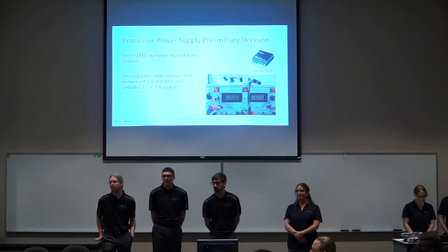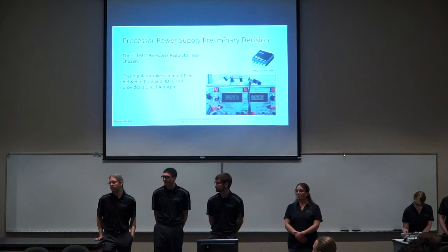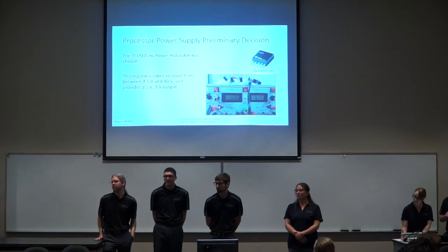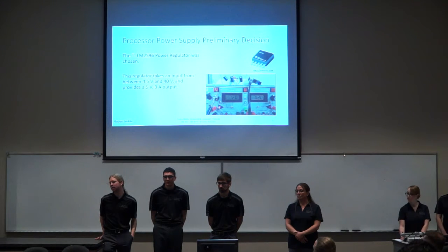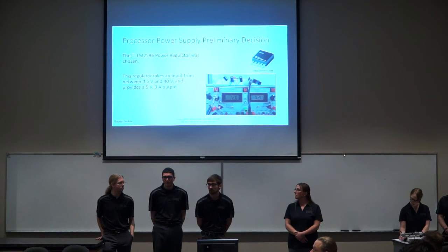Because you're dropping 15 volts at 3 amps. I did not notice a problem when I ran it to 12 volts, but I did not consider the power that would be consumed by the buck converter itself. I can speak more on this.